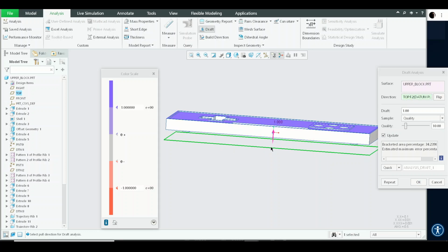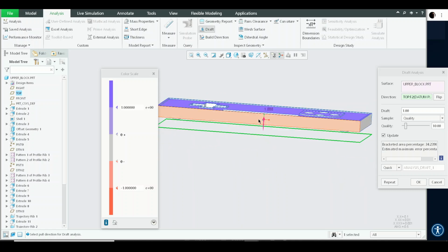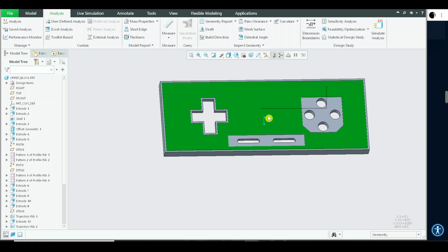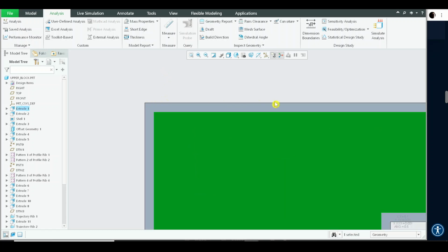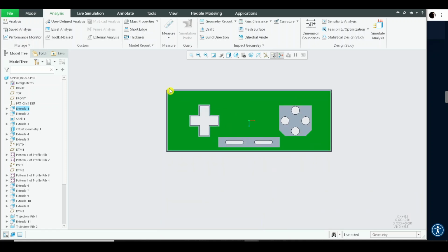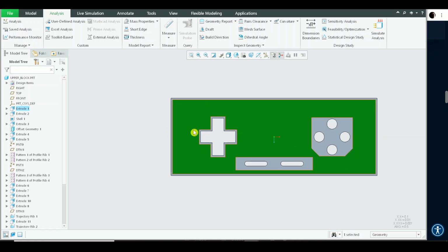Okay, now just try to imagine that you're pulling up in this direction. All right, so when you're pulling up in this direction, place the view in normal view and try to see what the vertical edges are. For example, this is a vertical edge. Now, is this vertical edge visible to you? It's not visible, so it has to be drafted, and ensure that it must be visible to you. Okay, that is the kind of trick we can say to understand in the beginning stages.